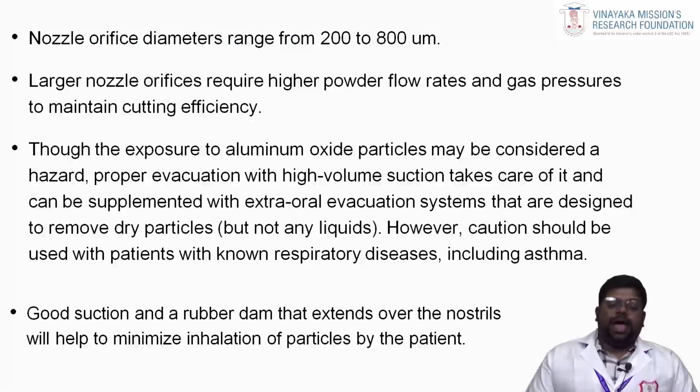Nozzle orifice diameters range from 200 to 800 micrometers. Large nozzle orifices are required with a high powder flow rate and gas pressure to maintain the cutting efficiency.